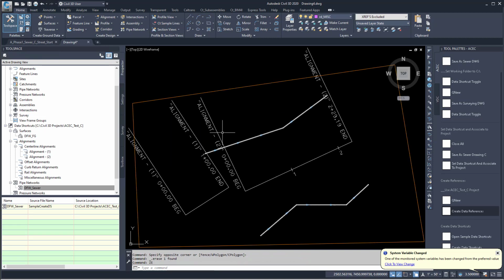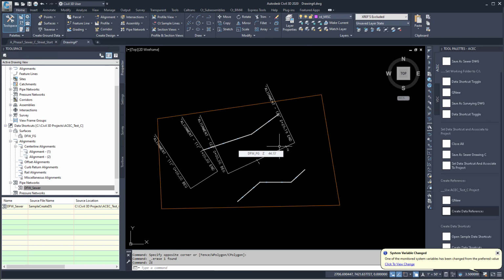I can do zoom extents, and then that's brought in all that information. In this case, I haven't set up the code to stylize the information, but if I had, you could expand this to assign the correct style based on the object's name and save the user some time rather than having to right click, create reference, and do them one at a time.